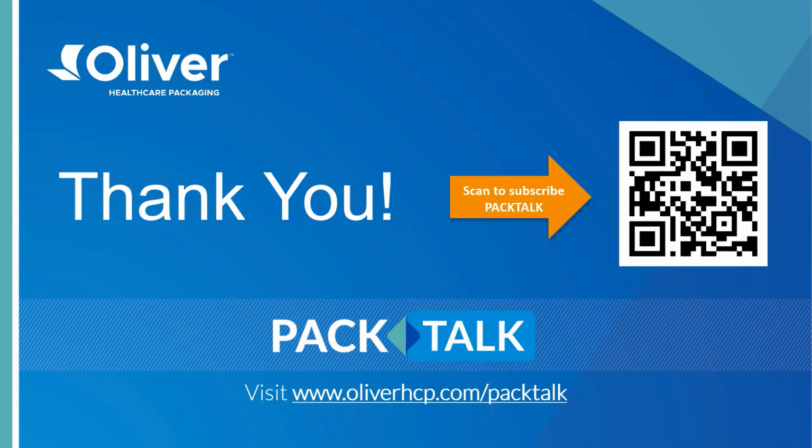Thank you. We got a few questions around the porosity of Tyvek and putting a flood-coated adhesive coating onto Tyvek and how it impacts EO sterilization and breathability. Can you speak to that as well? Yeah, sure. So the animation we showed was, you can imagine that we're flood coating the surface. In that particular application, that technology, you're counting on the drying process more or less to create cracks and crevices in the coating to allow for breathability.